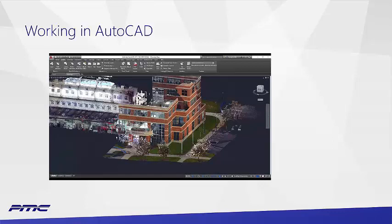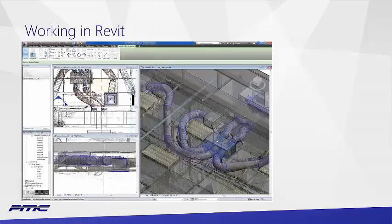You should be using one of the add-ins that are extracting that information from the point cloud for you. Same in Revit, okay? You just attach it. Revit is even simpler because there really aren't tools for working with the point cloud. It just shows up and it responds to all the standard Revit commands that you would expect. The one thing I would say in here is to make sure you pin it after you attach it, just so it doesn't accidentally get moved.